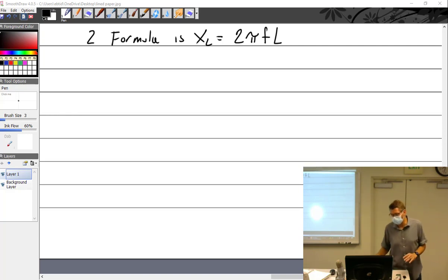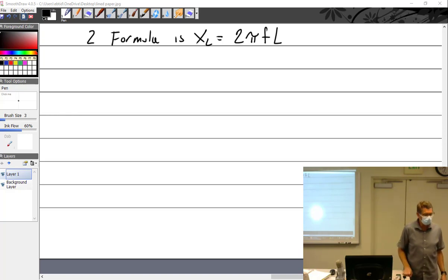So here I have something that's trying to block the flow of electrons. Well, what is that? It's like resistance. It's counter EMF, and that's like resistance. So here we're going to end up with this problem where we measure it and go, no resistance. Plug in the circuit, and you'll be like, what the heck's going on? There's all this resistance. Well, there is. But we don't call it resistance because resistance belongs to resistors. We call it inductive reactance.